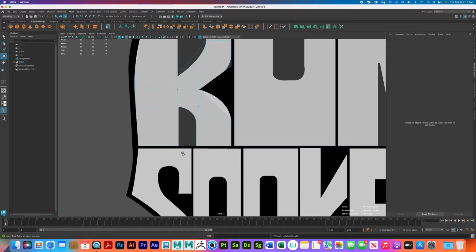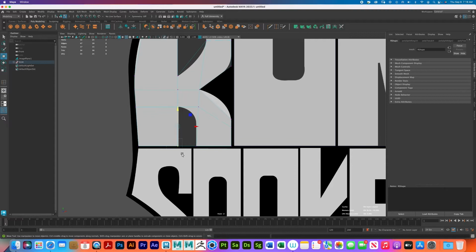Vertex. So if you ever have a situation, let's say where this is here, and you want to straighten it out, don't guess by doing this. What you can do is select both, press the letter R, and drag to the flat, and you're all set. Now we're gonna take this one, we're gonna push it over. You see what I'm saying? I don't want to do that. I want to take the R so it's aligned with the bottom. W, and I'm gonna push it to about there.